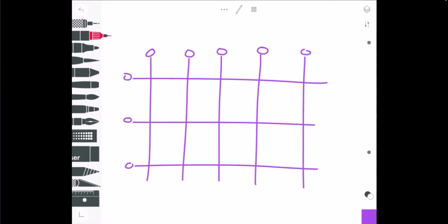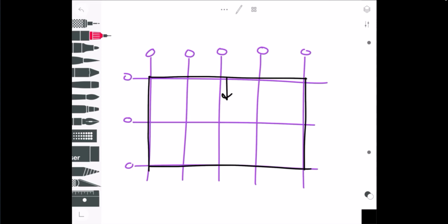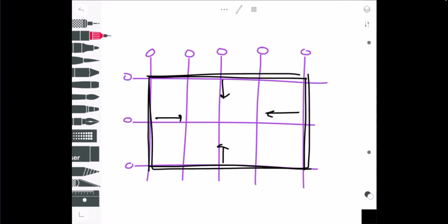Okay, so now the discussion gets to, how do we do this? This basically works with your grid system. What I've drawn here is some grid lines in a building. In this case, the building outline would be along the exterior grids right there. And again, we want to slope in from the outside. Generally how I approach this is a high point, low point sequence. If we want to slope the water inwards to some drains, we want the perimeter of the building to be the high point.